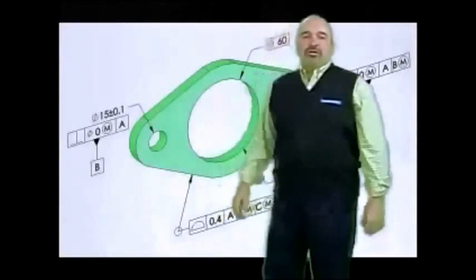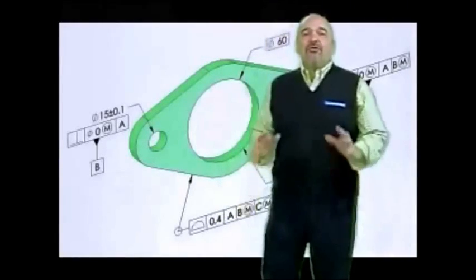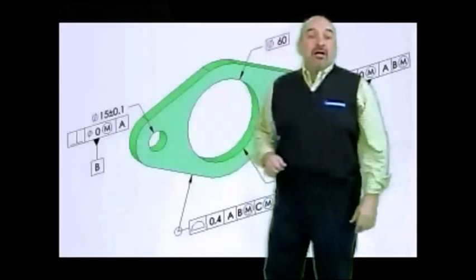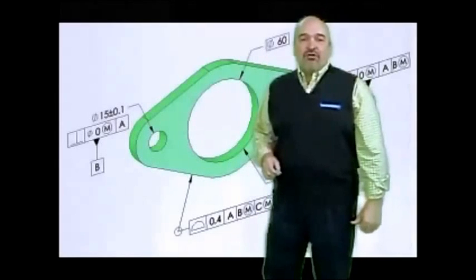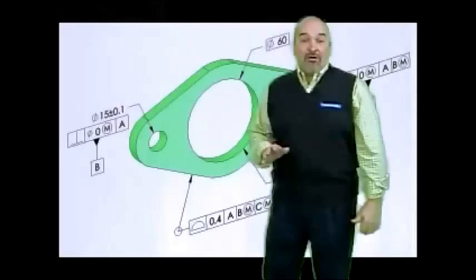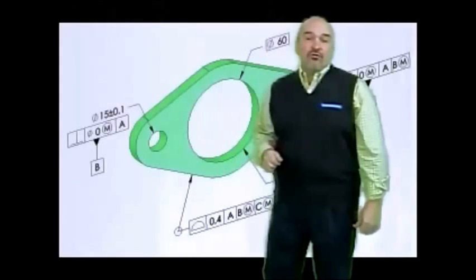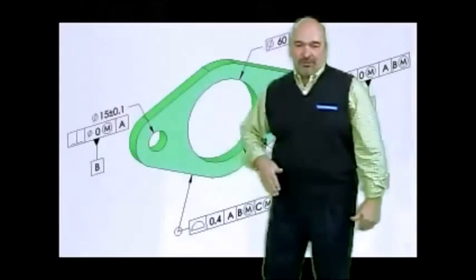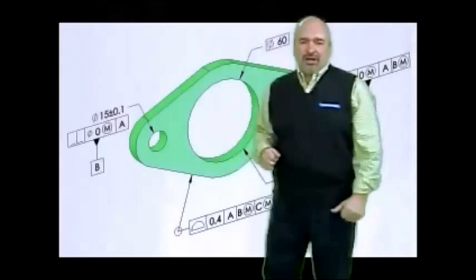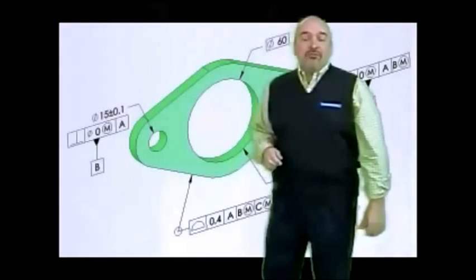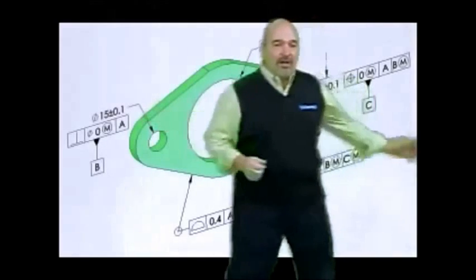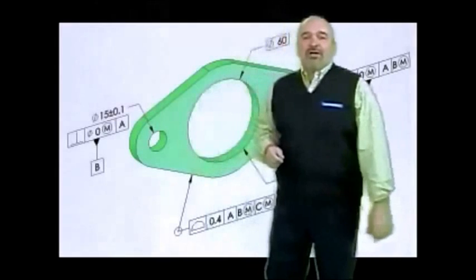I'm often asked if MMC can be used with profile. The answer is sort of. You are not allowed to ever apply MMC to the profile tolerance. You are, however, allowed to modify datum features referenced in the profile tolerance, provided they are features of size. Here, datum features B and C have been modified at MMC.